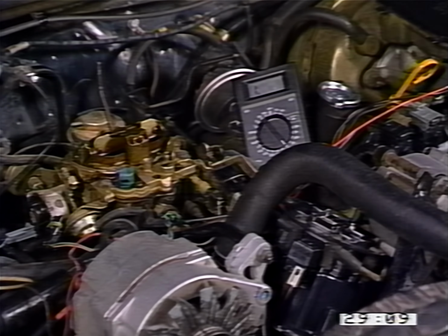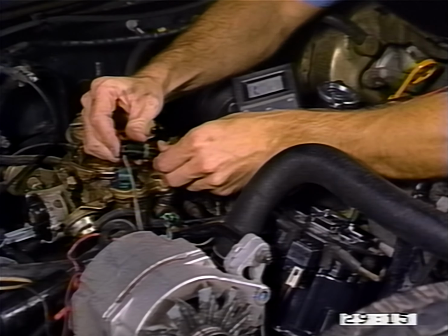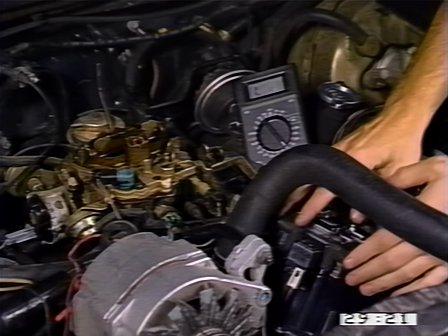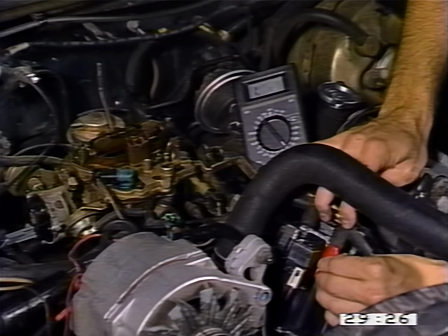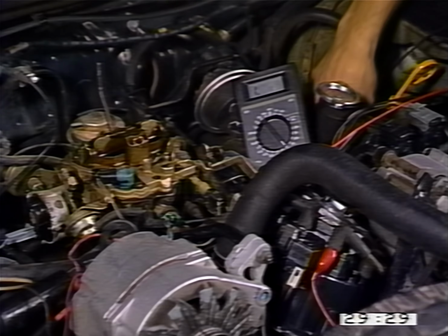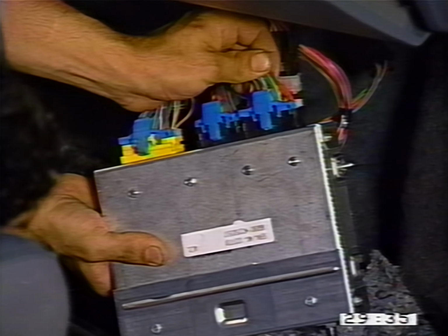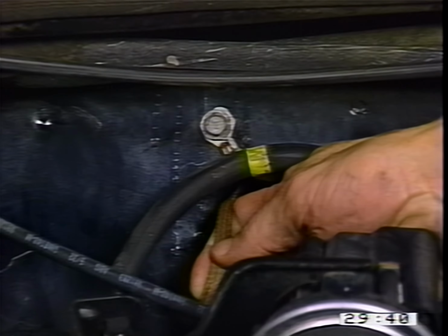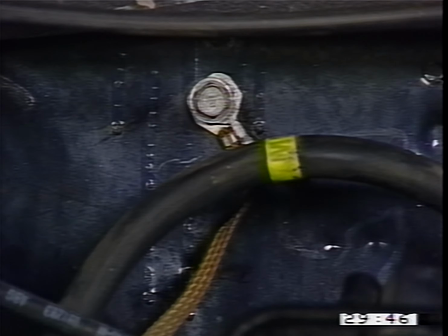Here's what to do to trace the source of an intermittent service light. Carefully examine connectors and terminals, making sure there are good wire-to-terminal connections and that they are clean. If you have any doubts, chemical cleaning is always a sound procedure. Carefully examine the secondary ignition system for either secondary leakage or excessive resistance as possible sources of intermittent fault codes. There may be an intermittent short to ground of the wire from the warning light to the ECM. Either the ALDL test terminal may be shorted to ground, or there may be poor ECM ground terminal connections. Either will cause a check engine lamp to illuminate without storing codes in memory.